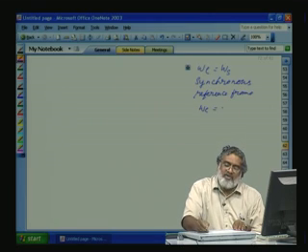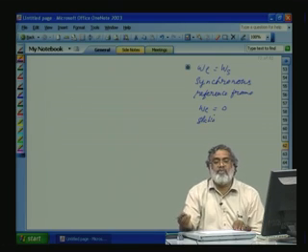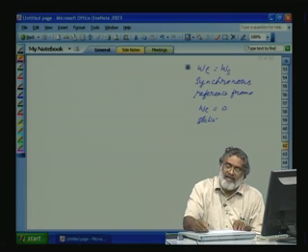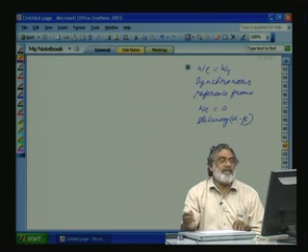If omega rho is equal to 0, then it will be the stationary reference frame. Stationary means omega rho is equal to 0, which means dq will be aligned with alpha beta, that is the stationary alpha beta reference frame.